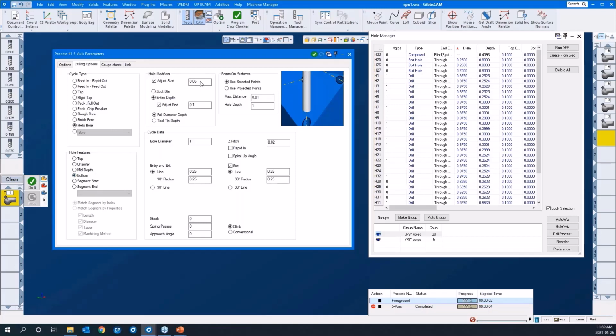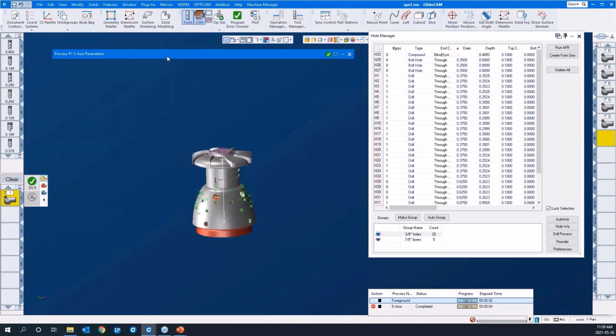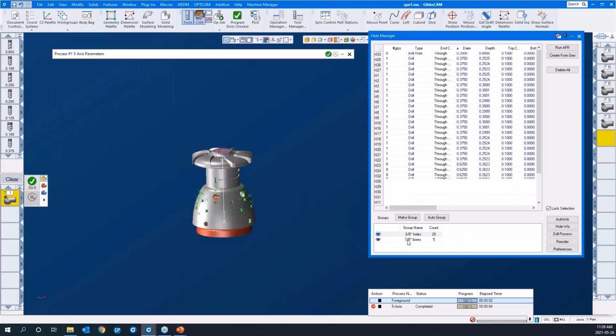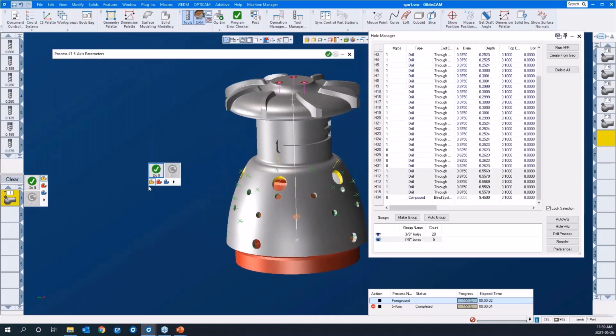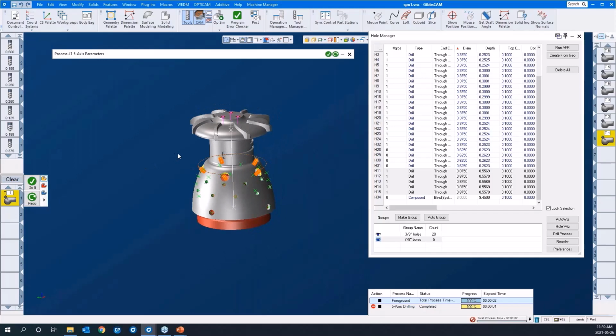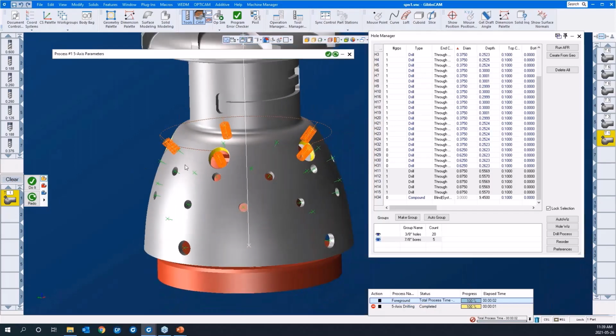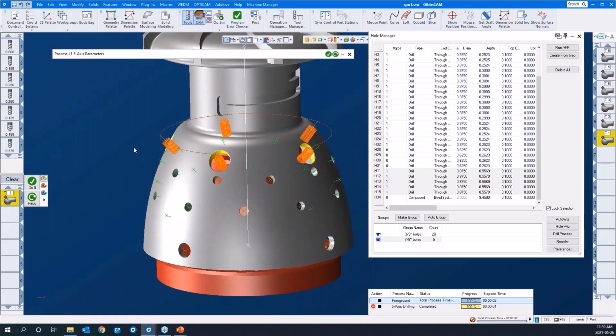We're using the feature to create the tool path. We're going to adjust so that the tool starts 50 thou above the feature and the entire depth breaks through the bottom by this amount to full diameter depth. Okay. There's gouge check and a link tab as well. Let's create the toolpath and see if they're required. I'll pick the 7/8 inch bores like so and say do it. It's as simple as that. Okay, it doesn't create a coordinate system. It supports, well, when we get to the drilling, it'll support drilling cycles as well.